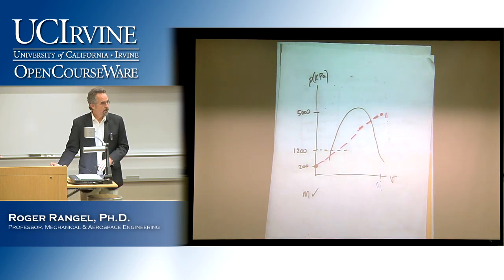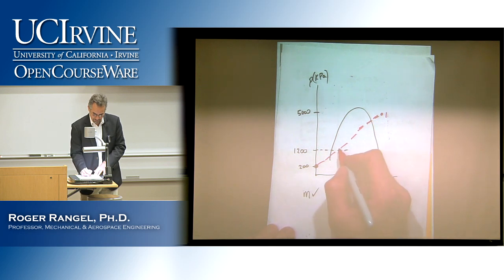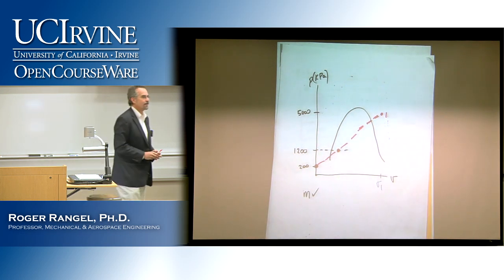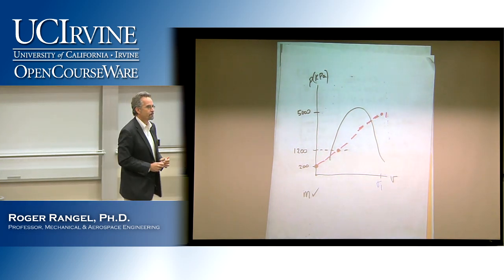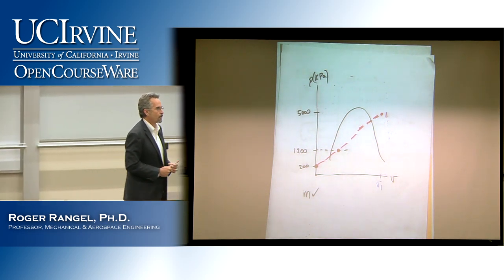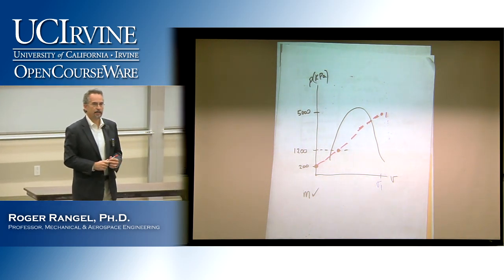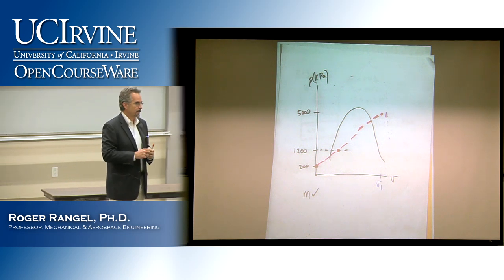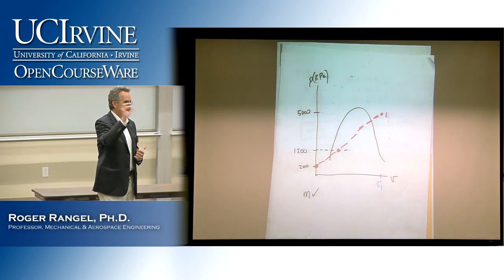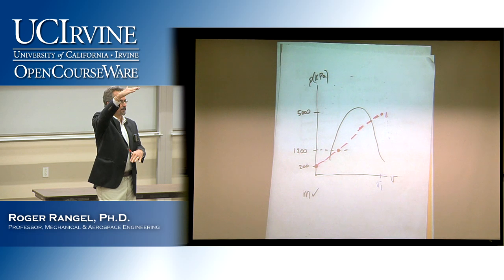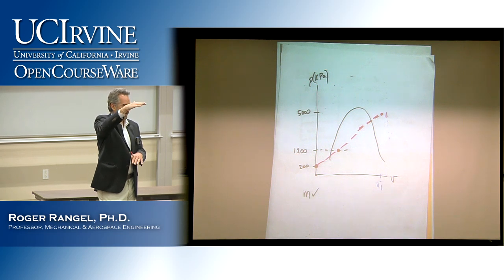But of course, for me, the story ends there. I don't need to go all the way down. Yes? So we're starting the piston at the bottom and then we slowly add water? We're not. We didn't see that part of the story. When we came to see the experiment, water vapor was inside the piston, and it was already full. All right? And we then started cooling the system down, so that piston is going to move down. And then we're told that we're going to end this experiment when the pressure is 1,200 kilopascals.